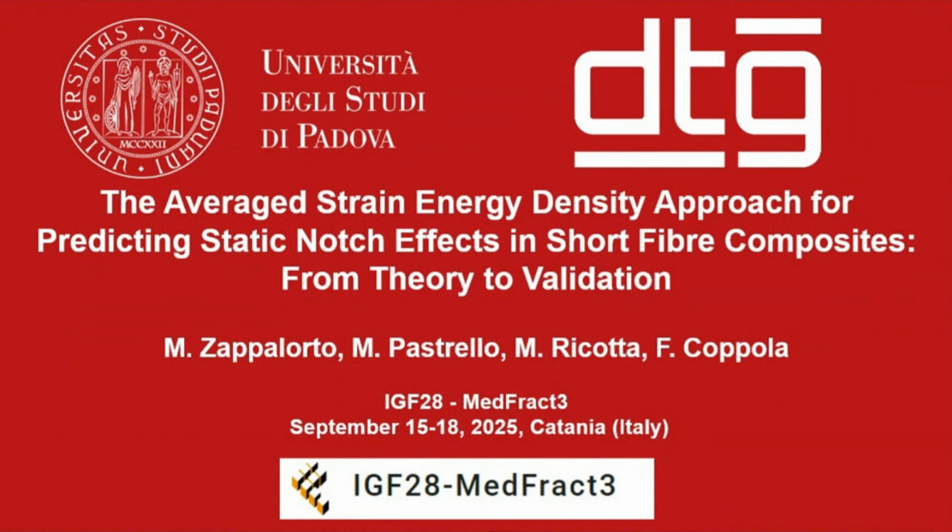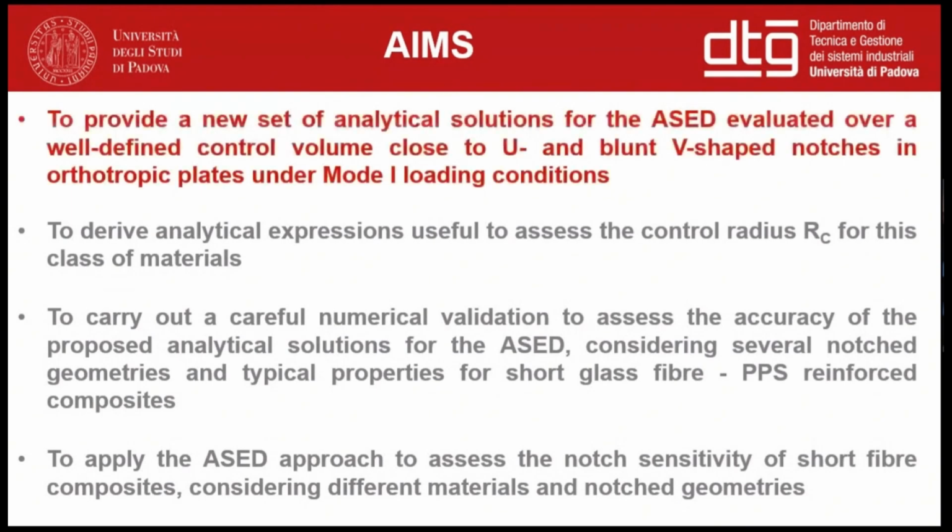So let me briefly introduce the aims of this work, where we have provided a new set of analytical solutions for the average strain energy density in notches, in particular reduced notches in orthotropic bodies, mainly under mode 1 loading conditions, as well as to derive some expressions to assess the control radius for this class of materials. Thirdly, we carried out a quite comprehensive numerical validation of the analytical solution determined for the strain energy density.